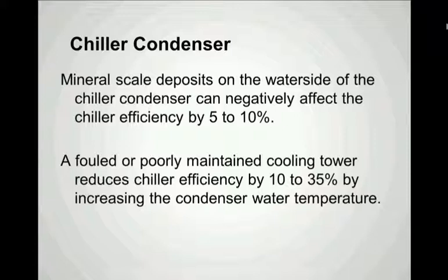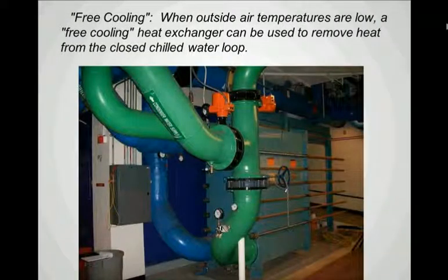And also we need to know that the cooling tower itself, the tower fill, must be maintained in a clean condition, because a fouled or poorly maintained cooling tower can reduce the chiller efficiency by 10 to 35%, merely by the fact that we're unable to cool the water to a low temperature, and that can adversely affect the condenser water, the efficiency of the chiller. So overall, cleanliness is a good goal for any water treatment program in any system that operates with heat transfer.